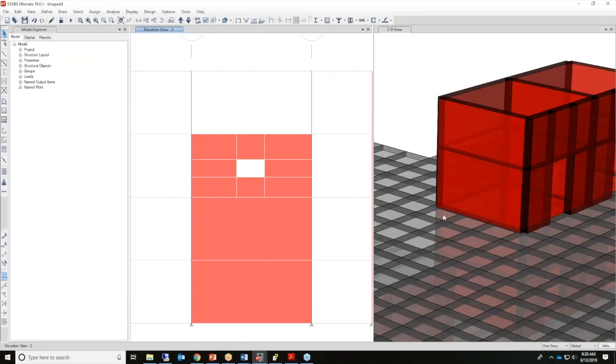So that was a very simple planar model for shear walls. But what if we have a floor slab? So here is a typical situation. We have a meshed floor slab here connecting to a wall as a part of an elevator core. So due to the edge constraints, you do not need to mesh this elevator core wall at these locations. Loads will be distributed automatically from the floor to the elevator core via the auto edge constraint tool.